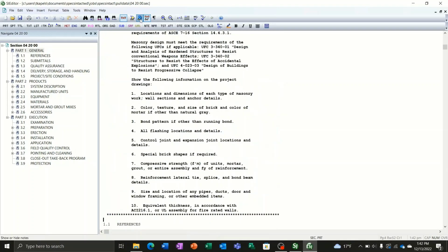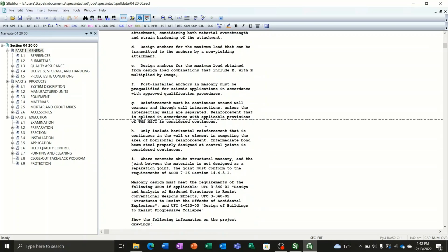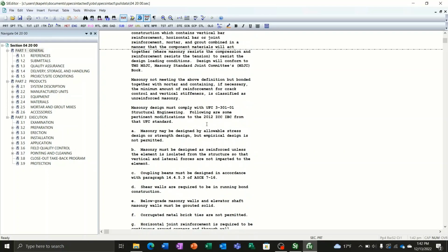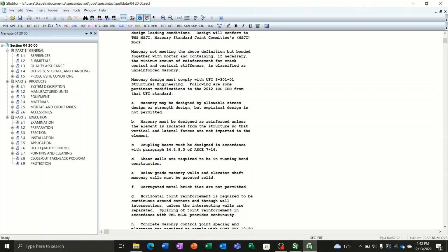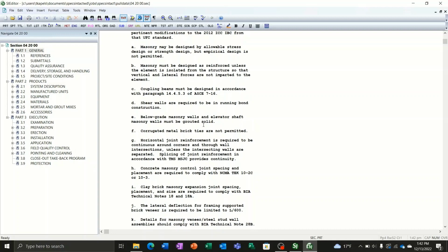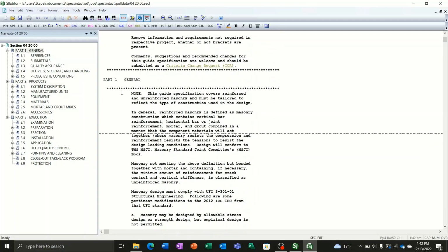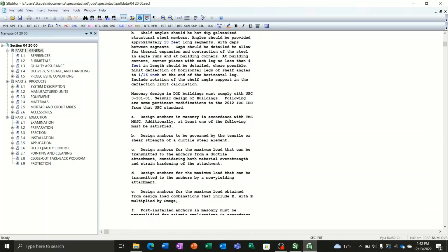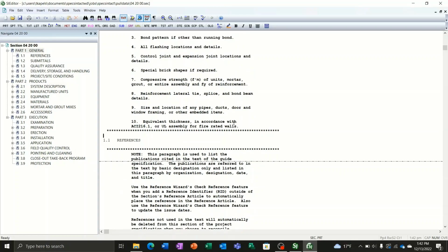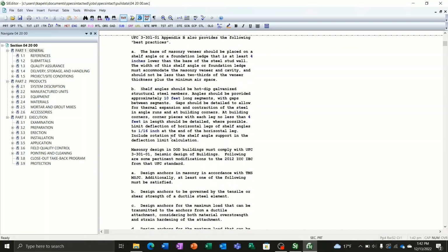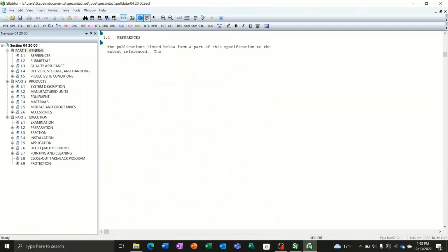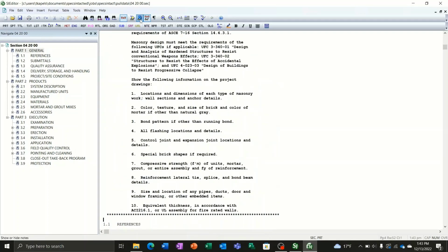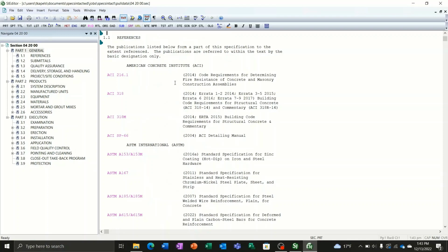And the next one is our editor's notes. If you're familiar with specification writing at all, most systems have notes in there to help the editor along. They give clues, hints, and tips on how the spec should be edited. Specs Intact is no exception. And usually these are indicated by a line of stars, and then all the notes, and then it ends again with a line of stars before it goes into the next section. So this is really just a visual tool to help with editing. You can have them on or off, it doesn't matter. I usually leave it off, and unless I have some specific question, I might flip it on, take a quick look, and then turn it back off again.